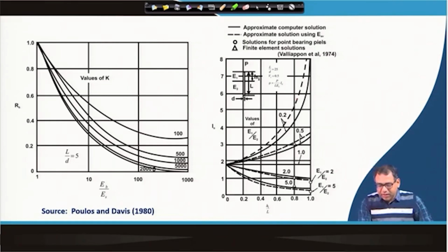Then you will also get a more or less close result, but the firm line takes the different E values into the analysis, not the weighted average. The dotted line is the solution for taking the average E value and using the concept of uniform soil. So, you use the firm line to determine I 0 for layered soil.